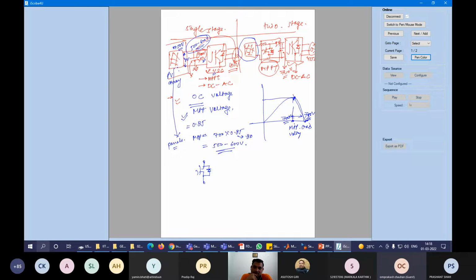It is the capability of blocking voltage. Whenever this switch is off, it can sustain the voltage as per the DC bus. Whenever you switch off the system, or whenever there is no current from the PV array but it is open circuit, you will get 750 volt as DC bus.